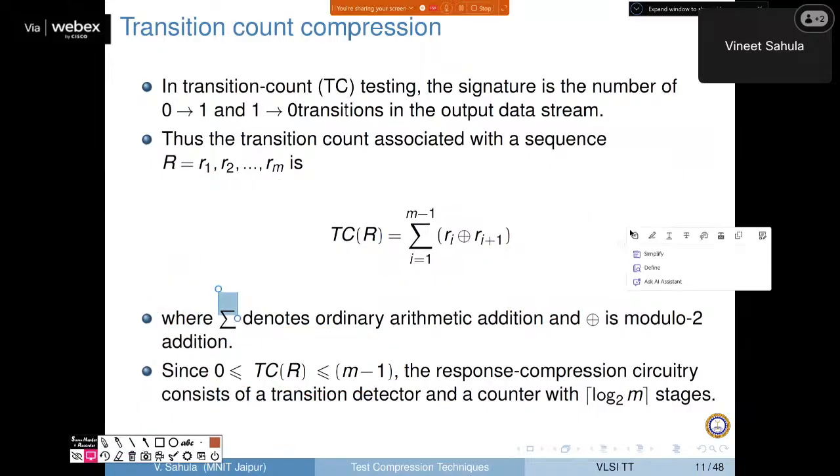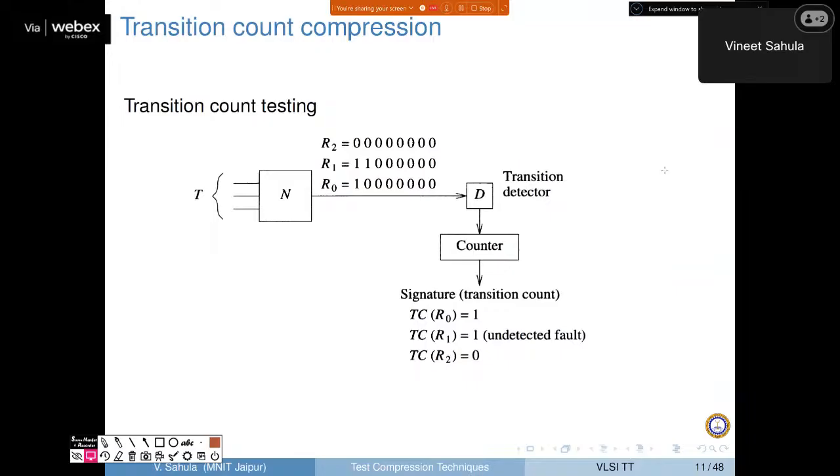So now I have initiated you with some understanding of mine conveyed to you. This still is the same way, right? So we just prepend the counter with the transition detector and feed that as a bit to the counter. It will count the transitions here. So a small modification can give this, and the transition detector could be just a flip-flop, right? For every transition, it will give you 1 bit kind of thing. Or just a simple detector you can design on your own way.